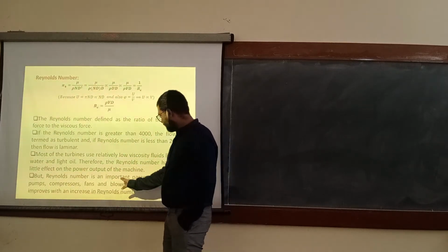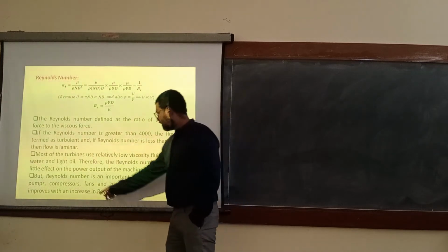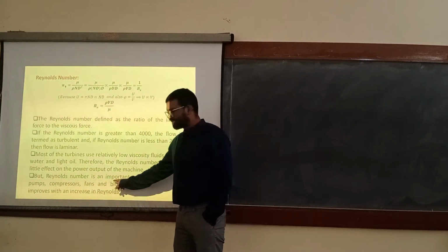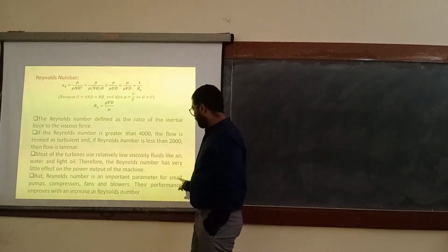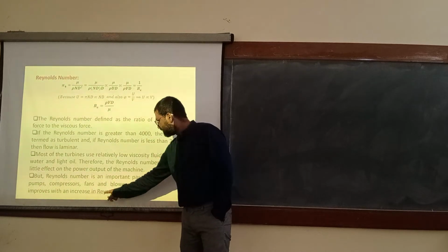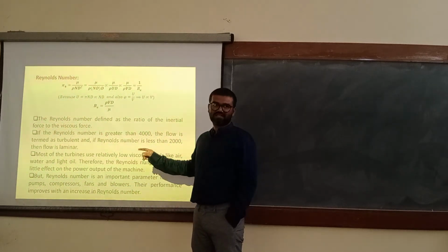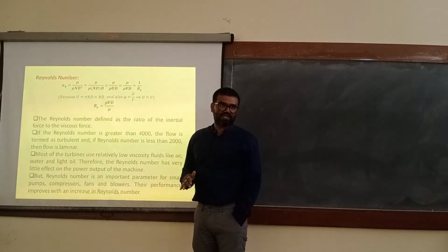But if you consider power absorbing turbo machines like small pumps, compressors, fans, and blowers, these machines handle highly viscous fluids. The performance improves as the Reynolds number increases. That means if the Reynolds number increases, the viscous effects reduce.